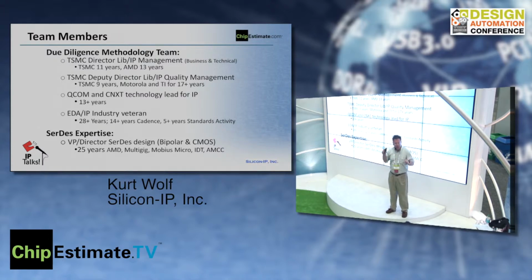Are the traces matched nicely? If you do silicon validation in that kind of environment and you expect to put that same IP block into a very low-cost board that maybe gets manufactured in Southeast Asia, where costs are kept to a minimum, that IP is most likely not going to work based upon what the test report shows, given a nice clean board and test environment.